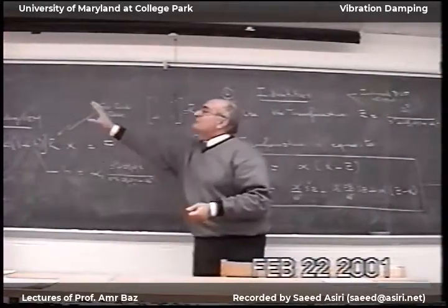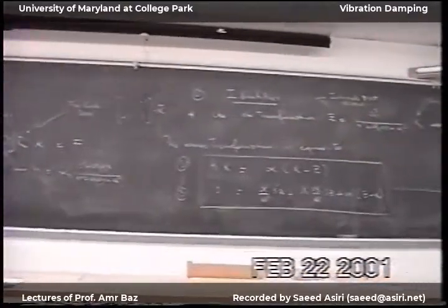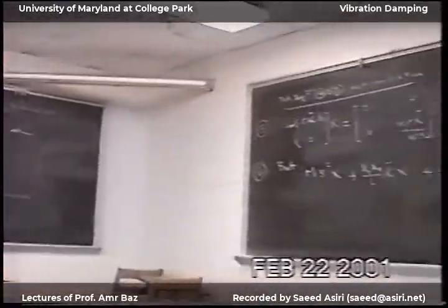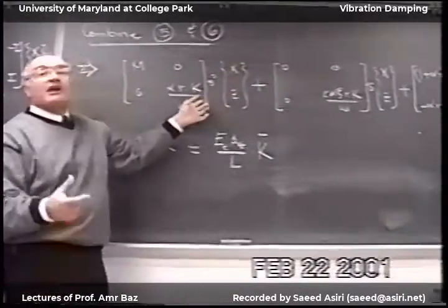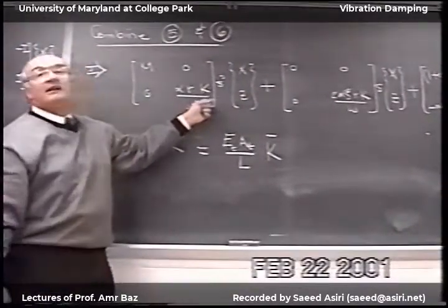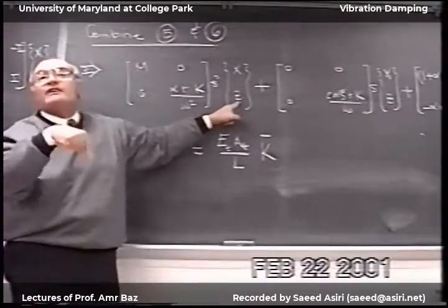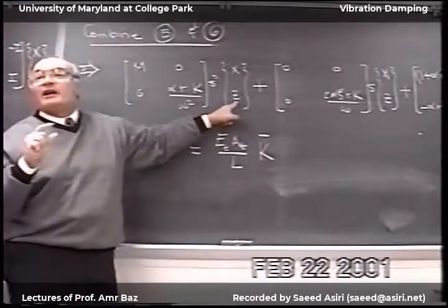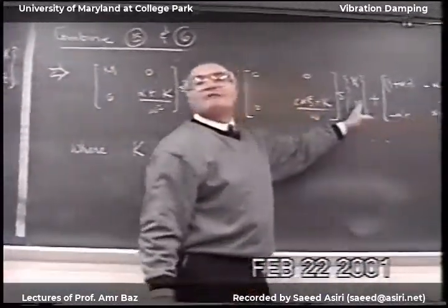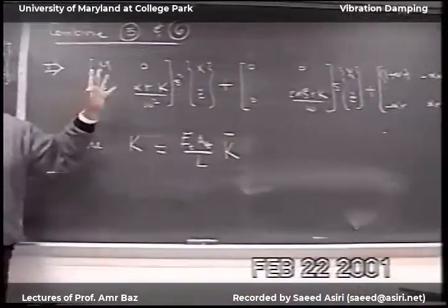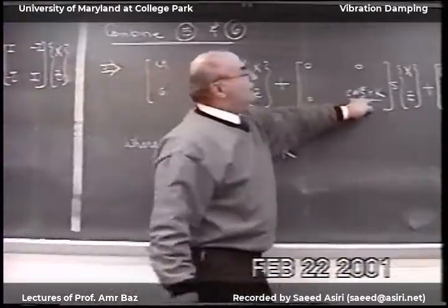Okay? These rigid body degrees of freedom, which are associated with the physical degrees of freedom of the system, are transferred, because the K is singular, to the internal degrees of freedom of the structure. So this is singular and singular. So now this system of equations, I cannot solve it, because I have singularity, singularity, and singularity.